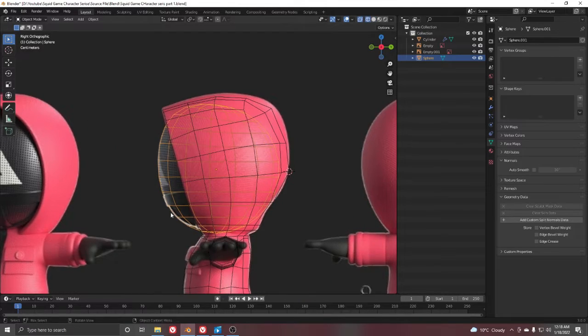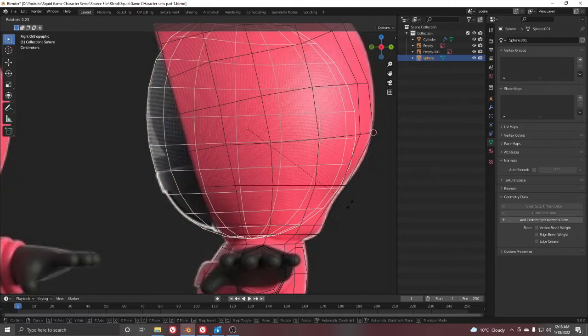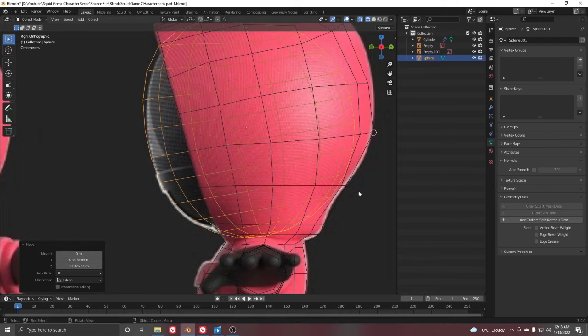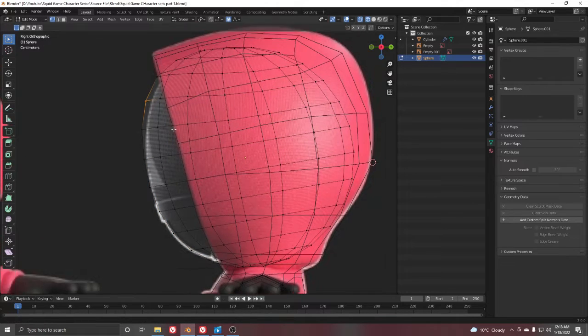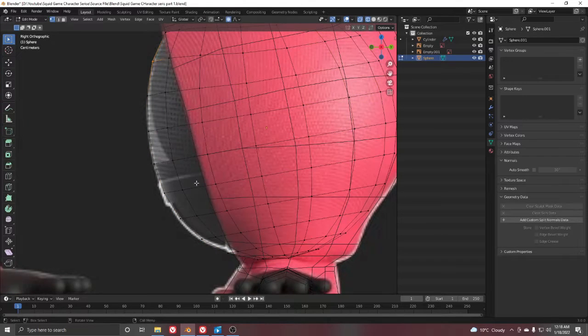Now we have to make this geometry, this shape. So for that I have to rotate my sphere like this and just move it around here. Go to edit mode again, do some simple proportional editing like this, and just select this edge loop with Alt, Shift and left click, bevel it with Ctrl B, and there we have it.